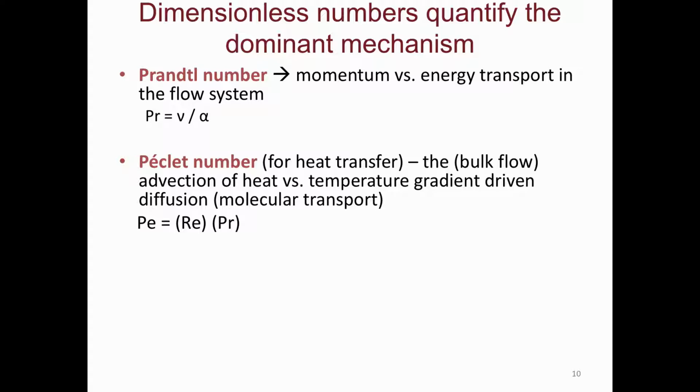But there could also be a case where my momentum transport is much more dominant in terms of the speed of the development than the heat transport from the heat gradient on its own. Then I technically don't need to look at the transport by heat gradient, because I'm dominated by whatever just moves in with momentum transport. And that's what the Peclet number for heat transfer is telling me. The Peclet number will exist also for mass transfer and will have a similar form.